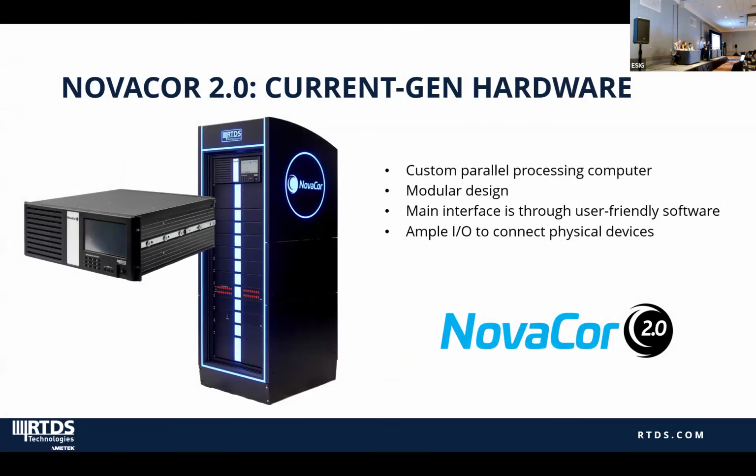So the RTDS simulator itself is a custom parallel processing computer. It's very modular in design. And of course, modularity allows us to customize the size of the system to whatever the needs of our customers are. And it is driven through a computer software, RSCAD, that's easy to use. So you don't have to be familiar with the ins and outs of the simulator hardware itself or the design. And of course, real-time simulation is primarily driven by the desire to test physical equipment. So we must have a lot of I/O available in the system to be able to interconnect with the outside world.